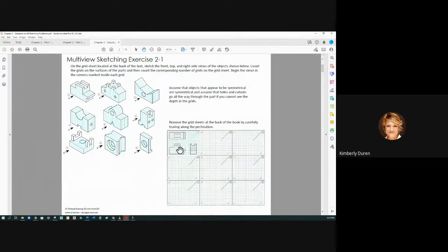So do you see that there is a primary view? The arrow points to the primary view, so always look at this, and it does change on other sheets. So this is what it would look like in the primary view. That is a hidden line right there. It's hard to see because this is so tiny, because I cannot touch that cut right there. From the top, I have a hidden line right here because there is an underside edge right there, that corner right here. And there is a back edge back here that shows a hidden edge right here.